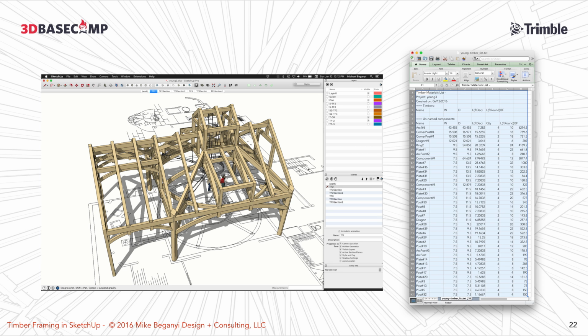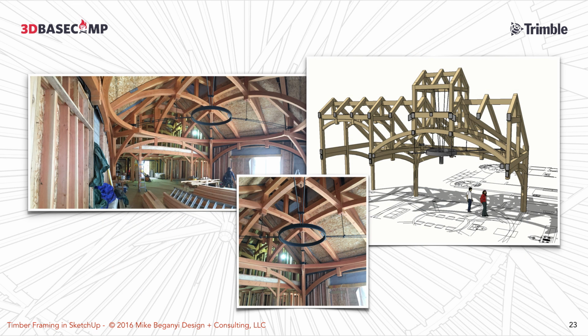This particular list will tell me the bulk board footage, and if it's fresh sawn Douglas fir, I know that I can put 15,000 board feet on a truck before I break the truck coming from the West Coast. So that's about half a truck of wood. Okay, so I've got to calculate. It's going to cost me $3,200 to bring it from the West Coast to the East Coast where I live. So all coming from the same model.